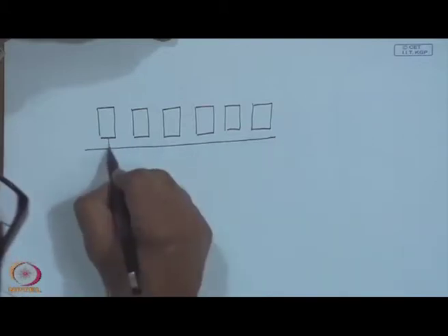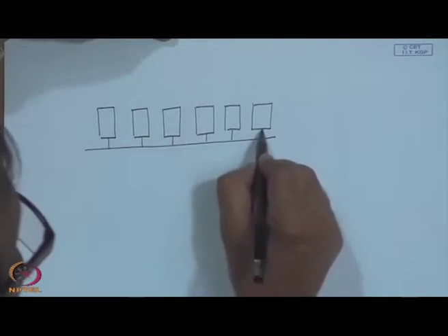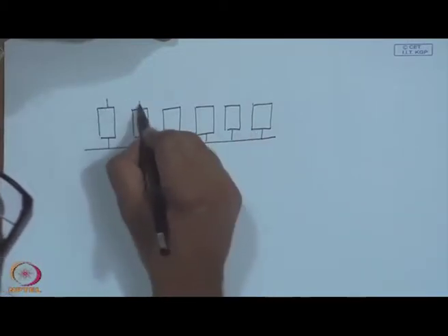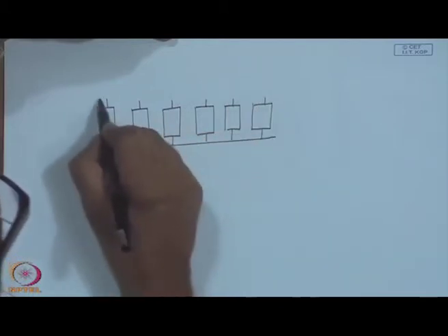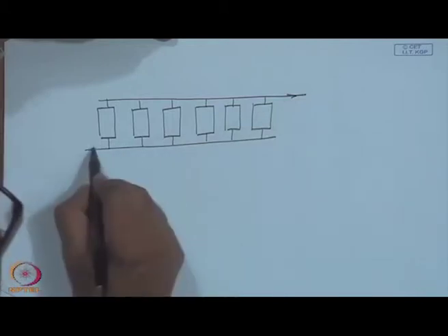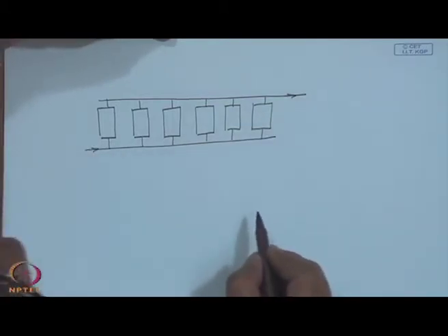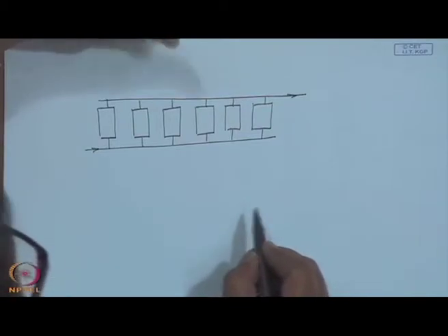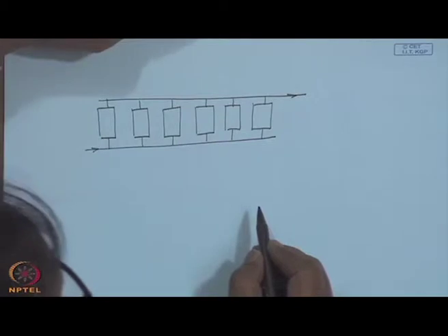So, let us say there is a large header connected to this, connected to this, connected to this, and all the 6. Then again the delivered hot water will come out through these 6 collectors, and I have some sort of a pressure balancing, so that the flow through each collector is uniform, in addition to the headers and risers that we discussed providing uniform flow in the collector.